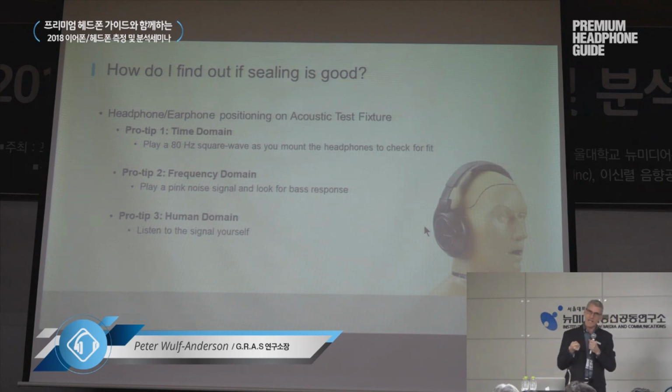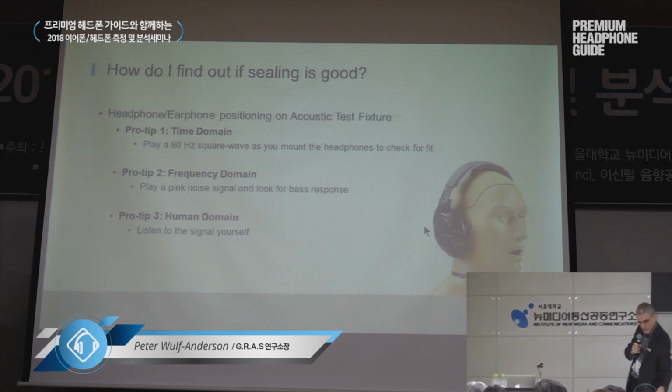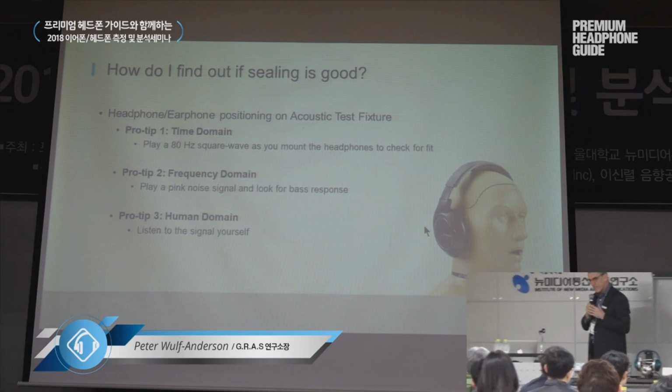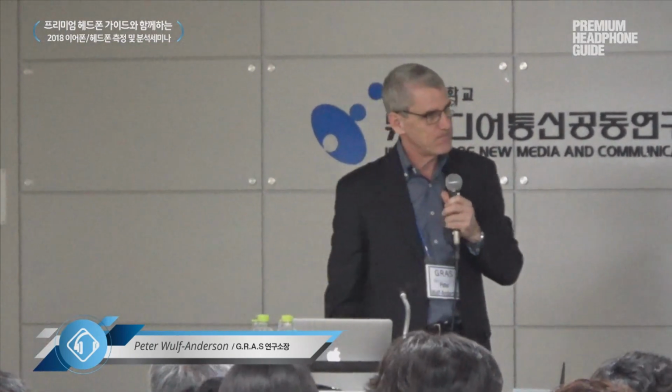Audio analyzers allow you to take out the measured signal and you can put another pair of headphones on, and then you move around the headphone over here. So you can move the headphone around until you have good sealing and listen to it at the same time. So that is another way of doing it.